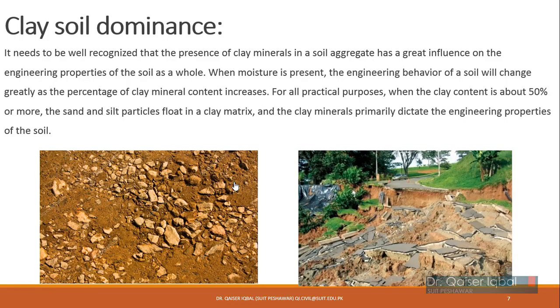After discussing these three mineral types of clay, you should always know that whenever clay is present in a particular soil, it will greatly influence the engineering properties of that soil as a whole. Because when moisture is present, the engineering behavior of the soil will change greatly because of the clay mineral content. So for practical purposes, when the clay content is about 50% or more, we should consider that soil to be primarily a clay soil.